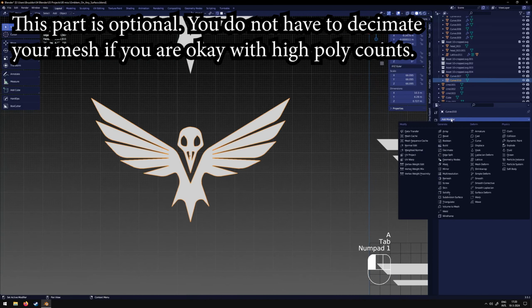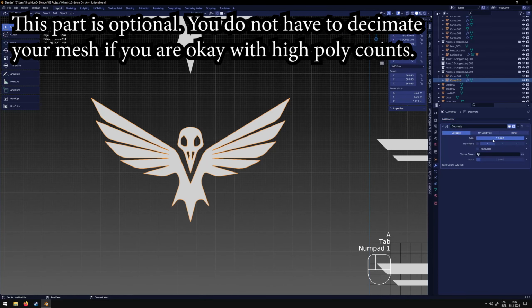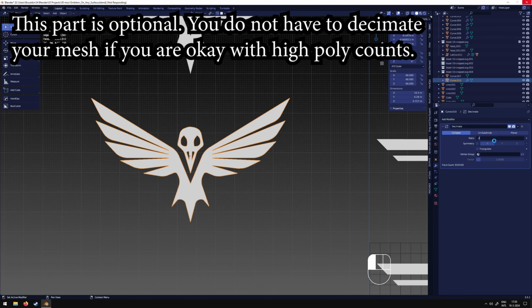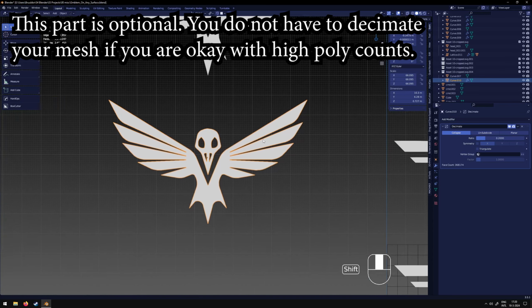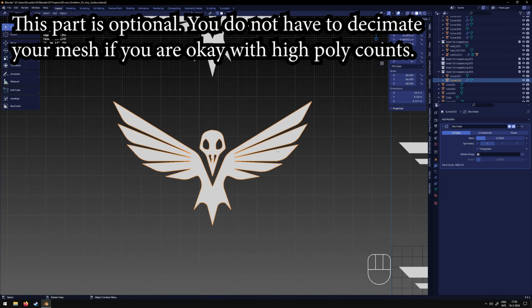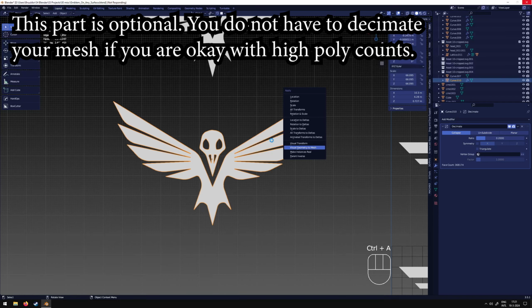So just to make sure that this remains within reasonable bounds, I'm going to decimate this. And it says it's got 900,000 face counts. Let's set it to like 0.2, see what it makes of that. Now this also may take a little bit as it tries to collapse the geometry into a smaller amount. Now 300,000, that's about okay with me. Let's visual geometry to mesh and then inspect how dense the mesh is by going into tab, edit mode, once this is done.